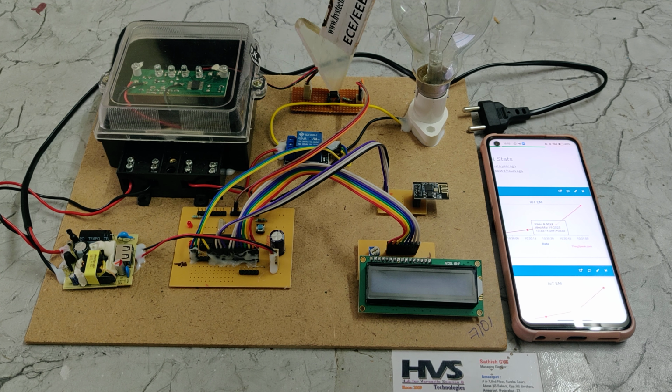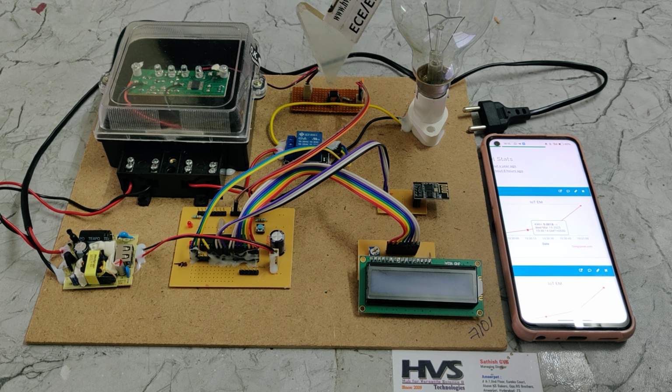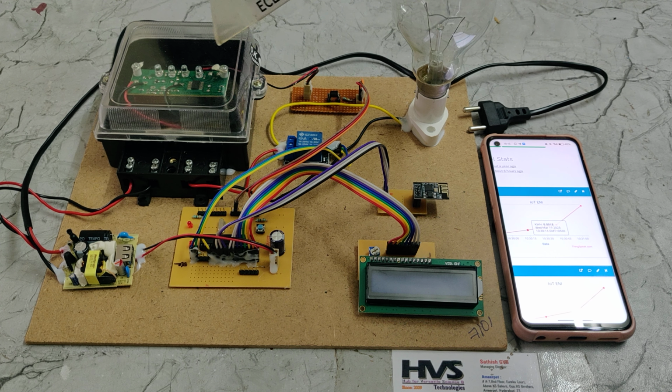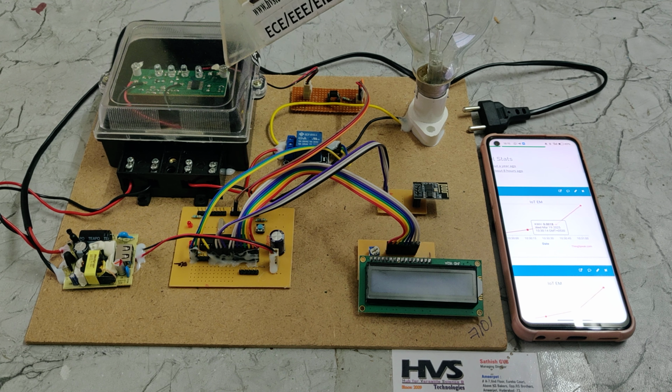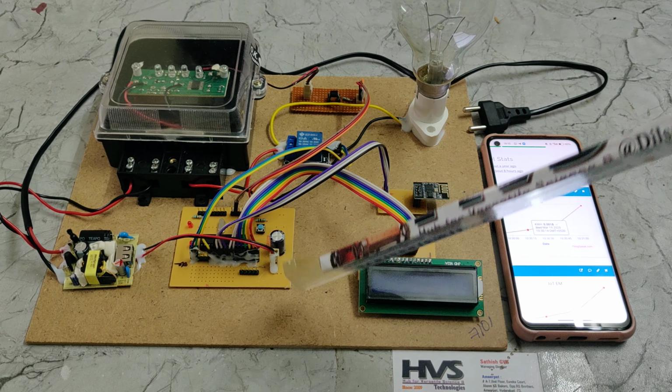So here the purpose of the optocoupler is, whenever we are getting the pulses, instead of giving the pulses directly to the microcontroller, we provide them to the optocoupler first, at its input pins. There is a primary side and a secondary side. This side gets the pulses, and the optically coupled IC provides the same pulses to the output side. Without this, if you provide them directly to the microcontroller and any short circuit occurs inside the energy meter, then the microcontroller may get damaged, which is the main brain of our system.